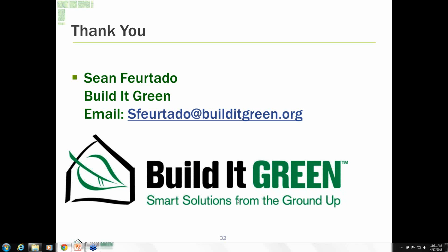So I got a question for the alternatives tabs. What if I have two different types of windows? So what you would typically do if you have multiple types of windows, like, okay, let's say I have a slider in some situations and I have double hung windows in some situations. Double hung window has lower performance than the sliders. You're going to be using those solar heat gain coefficients and U factors from the lowest performing window, not the highest performing window, and they're not averaged.